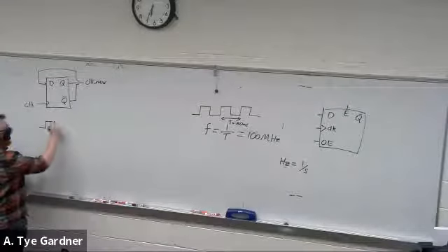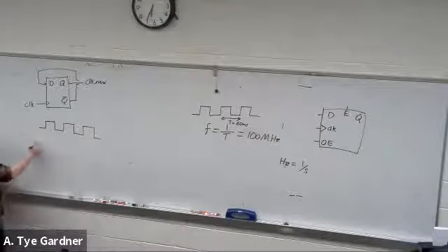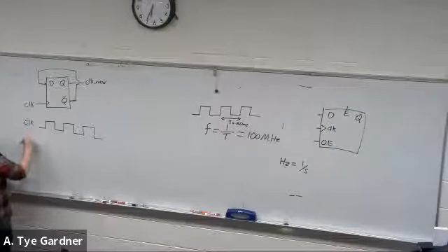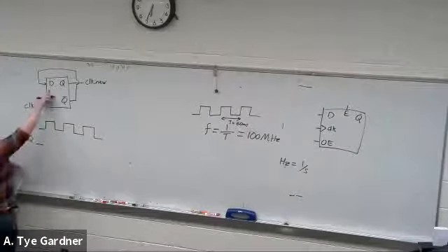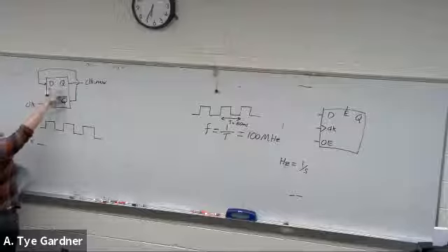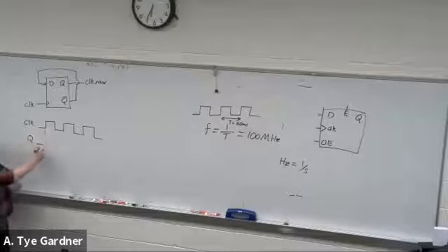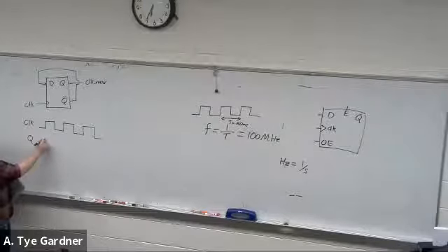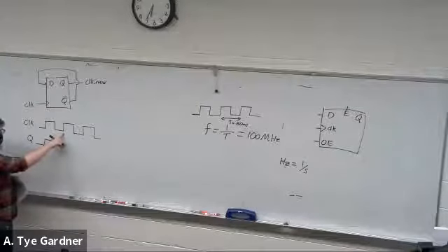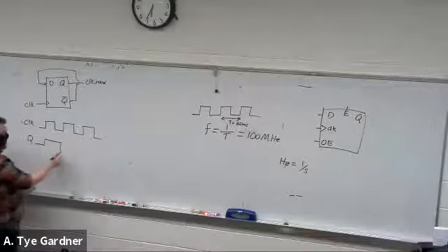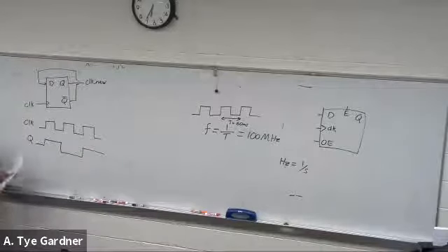Well, this is clock. And Q starts at 0. So clock, Q. So D, meaning rising edge of clock, Q is going to take D, which is just not Q. So if Q starts at 0, rising edge of clock happens, it switches. Nothing happens until the next rising edge of the clock. It just switches. We just divided by 2.